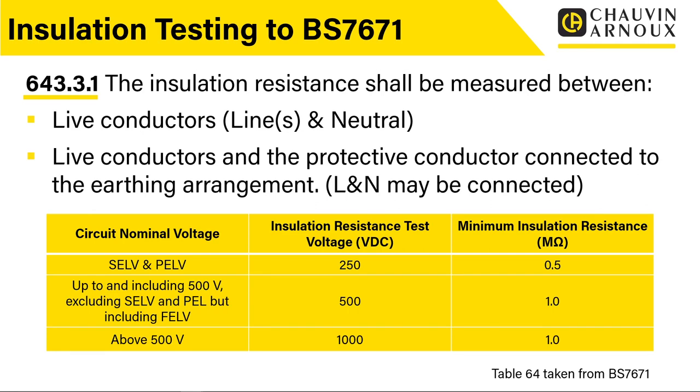Whereas if we were just checking to the cable with it floating, all we are checking is that floating conductor. So we're not actually checking to the general mass of earth and the general earthing within the installation, the equipotential bonding and all that sort of thing that's in there. So that is a fundamental change to how a lot of insulation resistance testing has been carried out in the past. And as I say, I can't remember how many versions ago, but this certainly happened quite a while ago. This test was made, certainly probably predating the 18th edition. I think this was towards the end of the 17th edition.